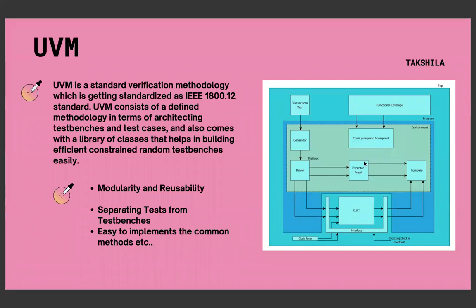And you have a BFM, which is a bus functional model or a C model, where you also drive the input and check what is the outcome. Then you validate your design's outcome and try to compare whether you are seeing the expected results or not. That's what is going to come.